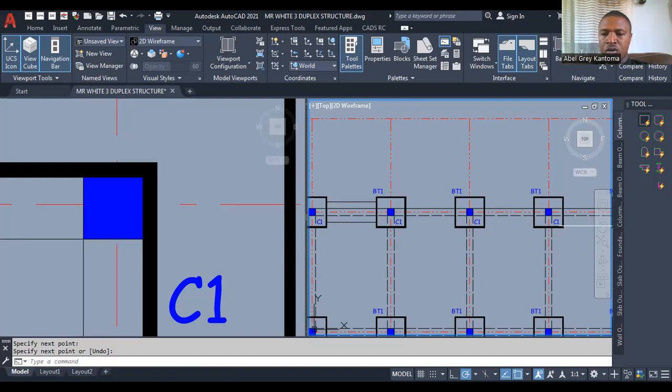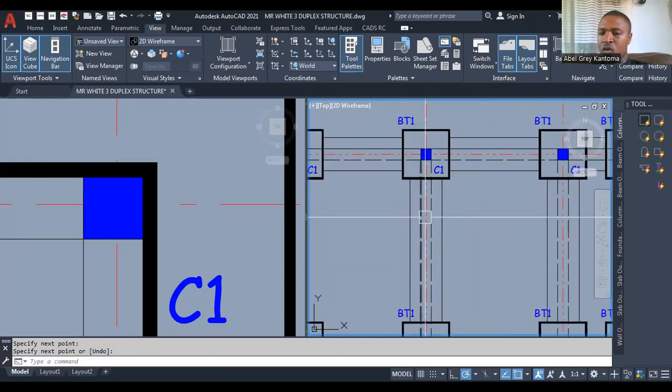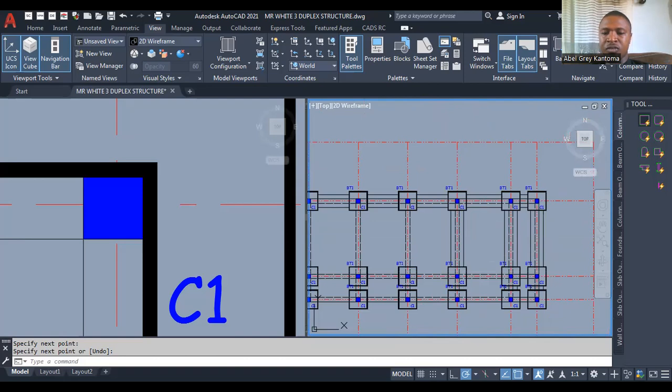These are all where we are actually going to dig. We are digging this area, the width of 230, 690. So you know you are going to have your walls at the center of that 690. So when you go to site, this is actually what you find.